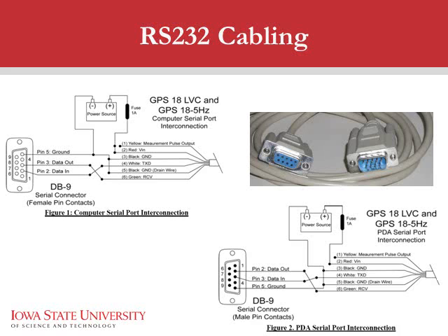Here's an example of an RS-232 cable. RS-232 cables are highly identifiable by the type of connector they have. This is a standard RS-232 connector. It's called a D-sub connector, or D-sub 9. The reason it's called a D-sub, the D indicates the pattern. It's noticed here that this has a D-type shape to it. The dash 9 indicates that it's a 9-pin connector. The sub indicates it's a sub-miniature type connector. But in practice this would be a DB9 or a D-sub 9 GPS connector.